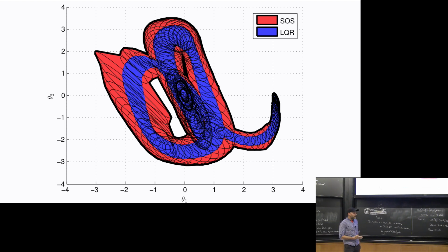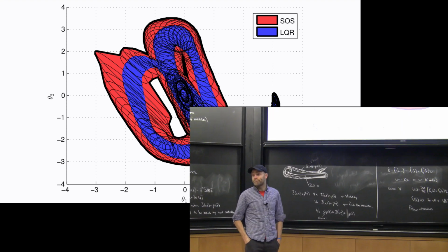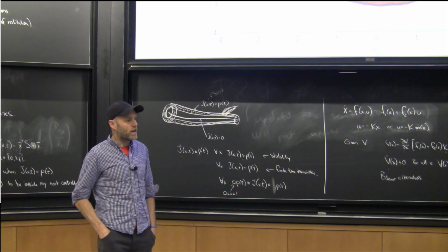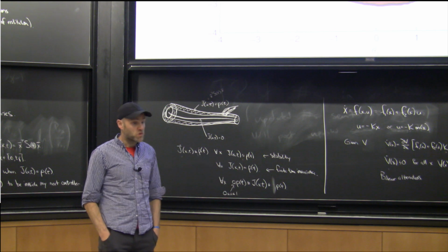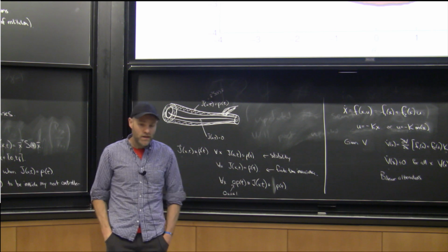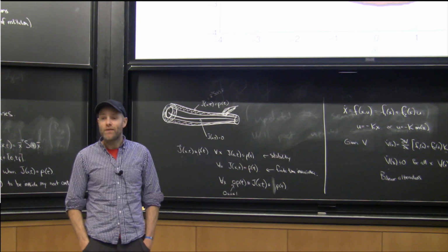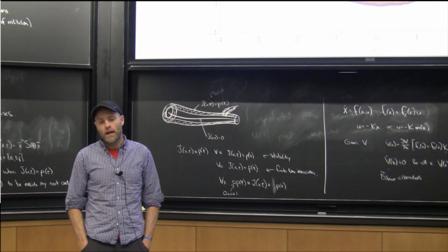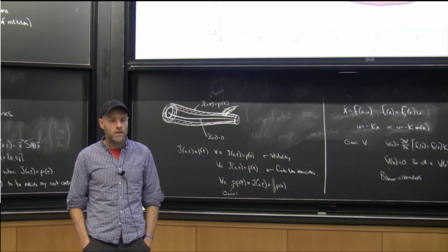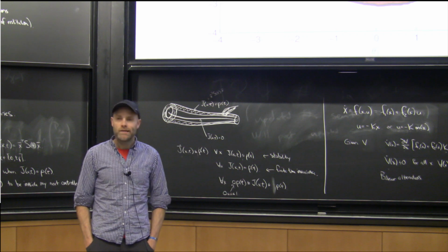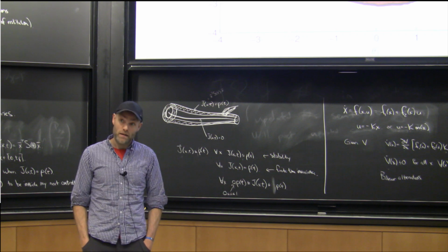But there's one thing that I just don't like about this at all, which is the reason we don't use this, for instance, for manipulation. I think it is good for vehicles. I think it's good for acrobots and cart-poles. I don't think it works for manipulation. And the fundamental reason is that we're still, so far, stuck in full state feedback.